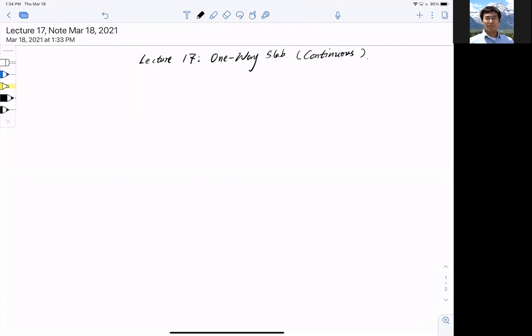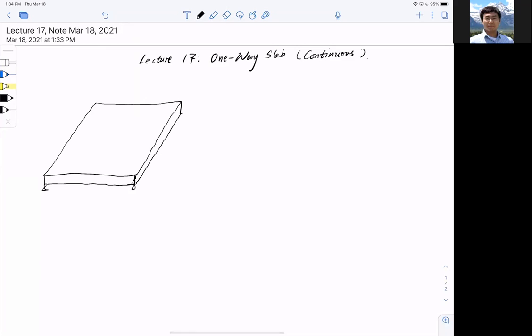Every time we talk about the simply supported condition, we draw a slab like this, and we show a support like this. And we show two types of reinforcement. I always use red for the main flexure reinforcement in the short span direction, which is the L1, for bending.